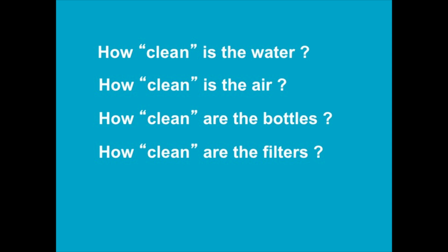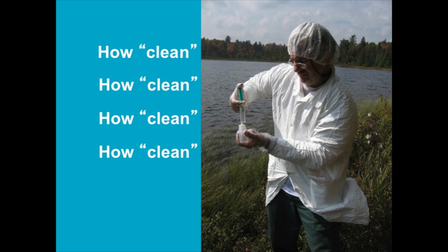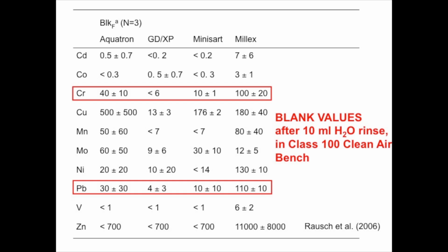Normally when you collect a water sample, you filter it. By the way, I don't filter any of these samples, and the reason is I don't know how to filter them without contaminating them. Normally when we go out into the field, we collect a water sample and filter it through a 0.45 micron membrane filter to get rid of the particles.